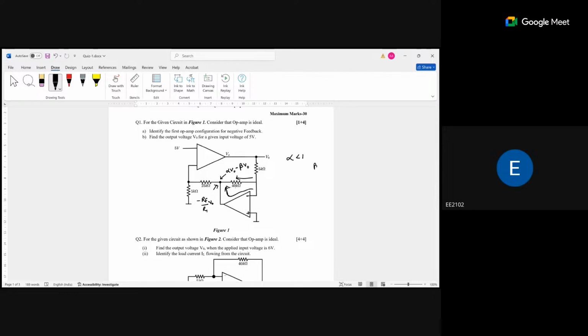And what is beta? Beta is RF 40 divided by 5, that is, beta is 8. So beta is greater than 1. So at this point, what are we getting? Negative voltage, because one current is passing through this one and one through the operational amplifier. So we take alpha V naught minus beta V naught. The value of alpha is less than 1 and the value of beta is greater than 1, so this particular term is greater than this one. So we are getting a negative voltage.